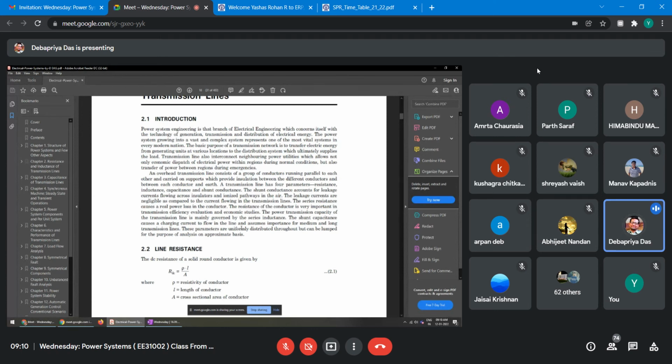For example, suppose 2 conductors may be there in one phase. Phase A, 2 parallel conductors, phase B, 2 parallel conductors, phase C, 2 parallel conductors, each phase 2 parallel conductors each. So if you make 2 parallel conductors, then what will happen? Current division will be there. Naturally, power loss will be less along the line. Naturally, voltage drop will be less along the line, because with 2 parallel conductors in each phase the equivalent impedance will be less, right? And therefore, at the receiving end, the voltage will be better, right?